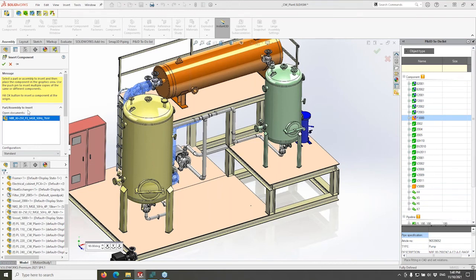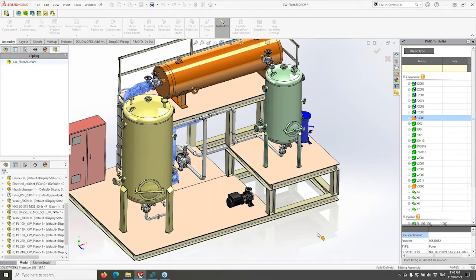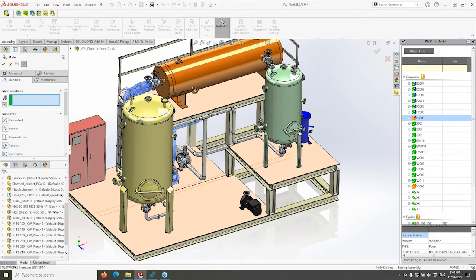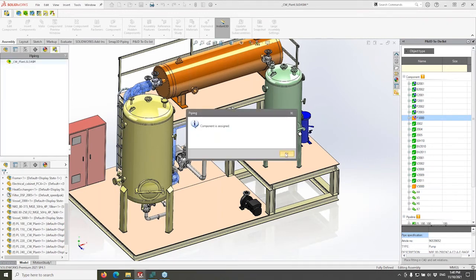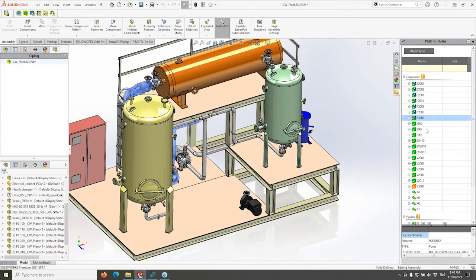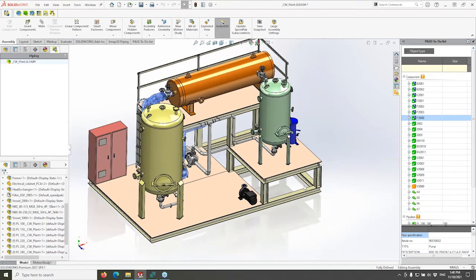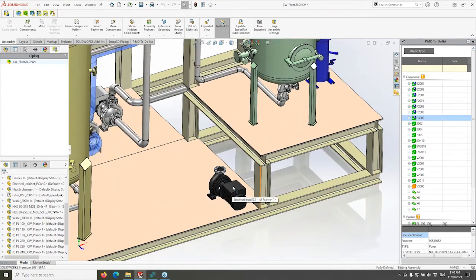Okay. And so from there, we can just use our normal SolidWorks tools. This has a mate reference in it, so I can use my SolidWorks Smart Mates to pop that into position, or I can go through my normal mating process of creating my mates manually if you wish. So now it's assigned that component. It turns it green. Life is good. We can move on here.